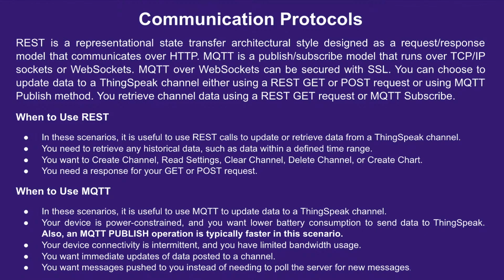And that is exactly what we want. Our devices need not worry about continuously polling data from the server and checking whether new data has arrived or not. This will consume more power, and we know that our microcontrollers are low power devices. We have a battery constraint, so we need to preserve our battery. For that, MQTT is extremely good, and how it helps us is that each time the data is updated in a channel, you automatically get the notification and updates to your device.